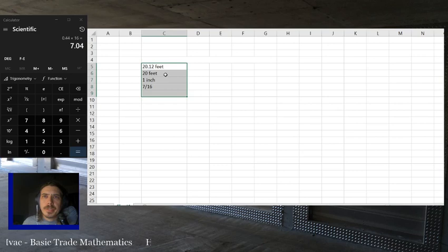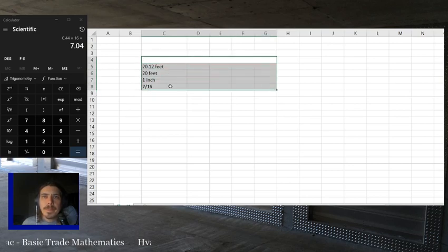And obviously, there's plenty of YouTube videos out there that can probably help you learn to put basic formulas into Excel. But where this is really going to help you is when we get into complex equations, just like we just did with equivalent diameter of duct. When I give you exercises on doing ventilation air into commercial buildings, if you can sit down, come up with a simple Excel formula and plug in those numbers, you'll be able to do that a lot faster than doing every single one by hand.